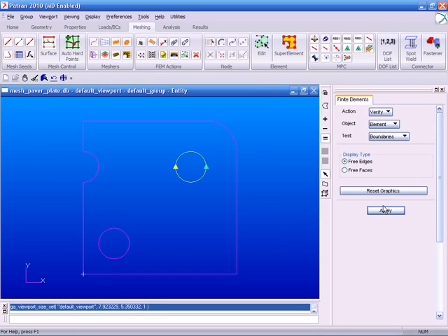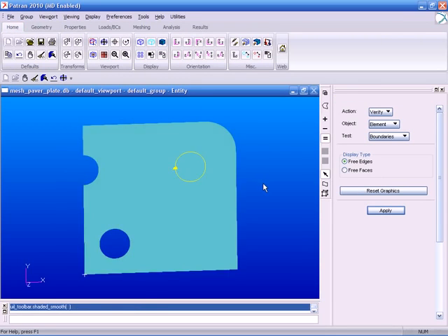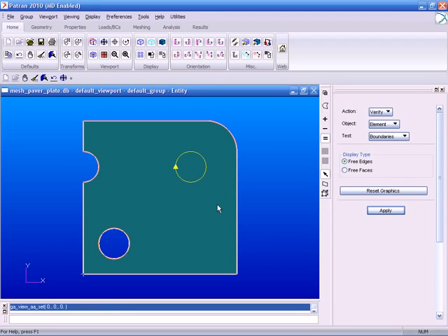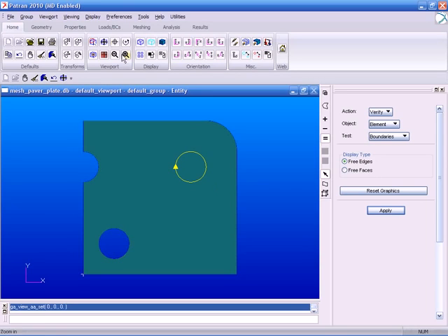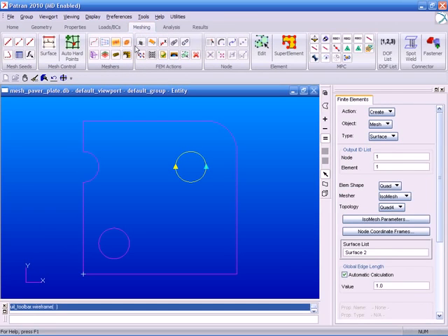Now I've opened a model of a more complicated piece of surface geometry. I can shade it and see that this geometry has irregular edges, holes, and has associated geometry here in this yellow curve that I want to be respected when this surface is meshed. So this will require more complicated meshing. So when I go to my Meshing tab and select Surface, this will require a paver mesher.